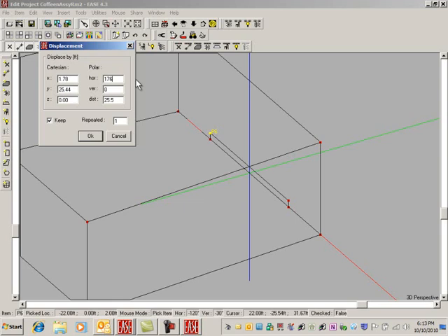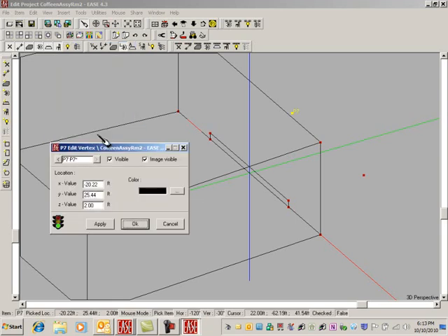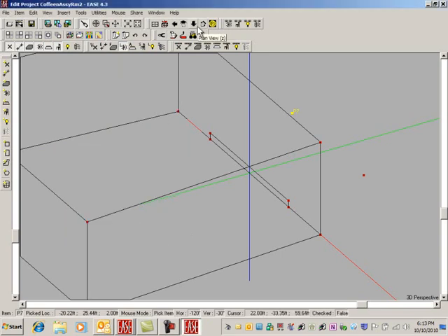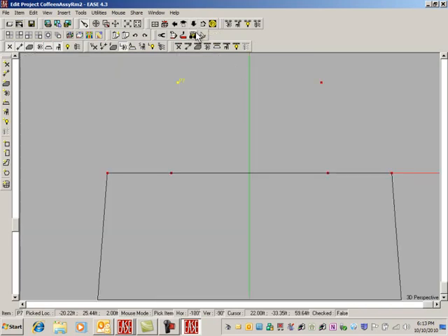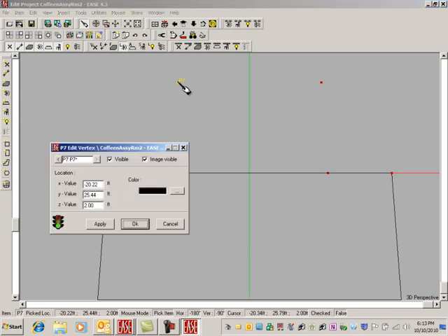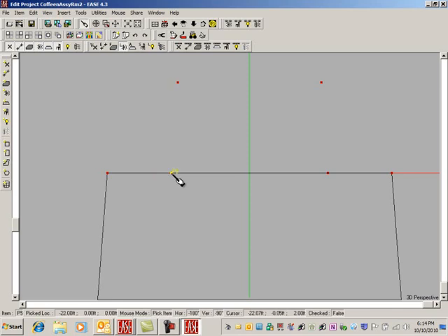So I think I'll make a face here again. I've got the vertices there. Type F. And I create an inside face, the back of the stage. Here, like this. And over to here, it's still symmetric. Create the face. Sure. And let's make it chipboard. 2 layers of 5/8. Okay, we're getting along here pretty well, but